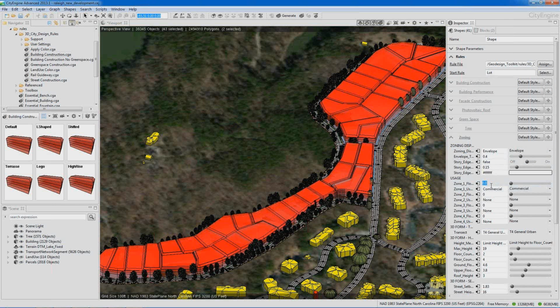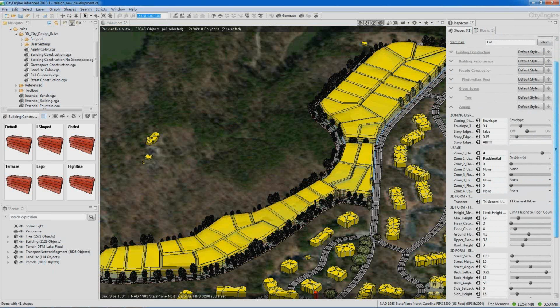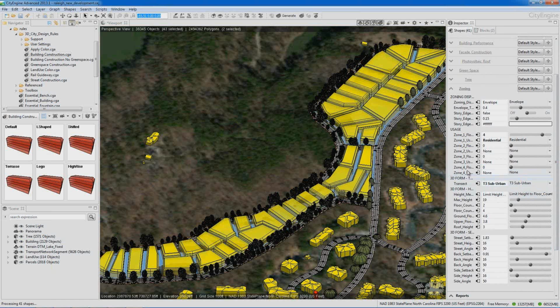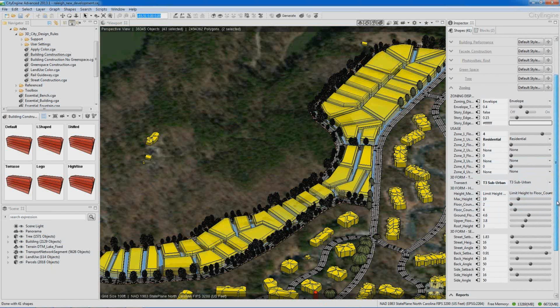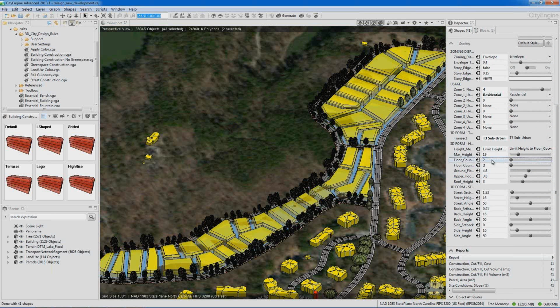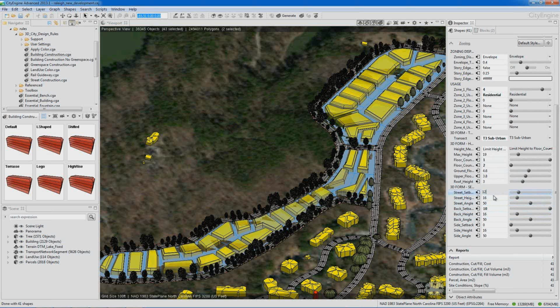And what this means is we can encode or codify the full volumetric limit that the building is going to be placed within on the site to try to preserve visual character or other sorts of character of that area and keep it within certain ordinances. This can be handed off to architects to make sure that they build within the specific volumes as well for cities, because there are sometimes issues with that in master plans and checking master plans. So we can change the setbacks for these volumes, and we can change the height tapers, all sorts of things. These can be used in urban dense areas or in suburban areas, as you see here.